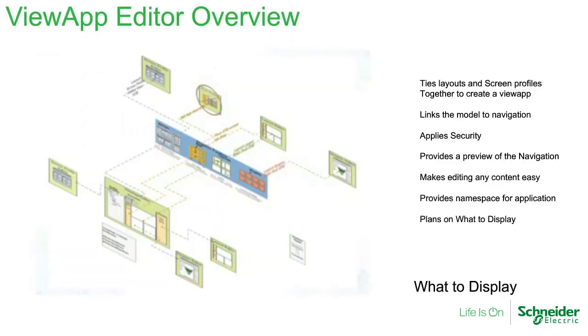Lastly, once you have your screen profiles defined and your layouts, there's a ViewApp editor that brings all this together. It takes all the definitions of the screen profile editor, of symbols, of layouts and of your model, and creates a view application. This view application looks very much like your InTouch ViewApp. It's the same definition. It's just a new icon in the IDE, and you can deploy that to a view engine just like you could an InTouch application. And you can deploy them side by side and run your InTouch OMI next to your InTouch for System Platform application using the same content.